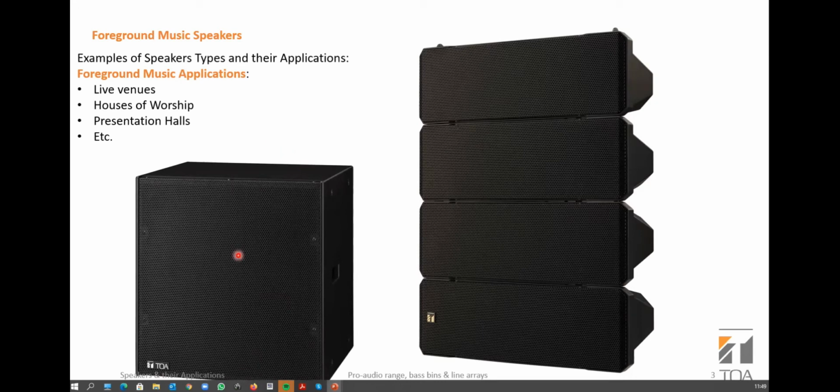So this is when we are talking of seriously high power, when we are using this kind of professional audio speakers, as well as these for live venues, houses of worship, presentation halls, etc. These are normally 8-ohm speakers. You will also notice when we were dealing with the commercial audio side of amplifiers, I was saying 30 speakers for a 30-watt amplifier, for example, 120 speakers for a 120-watt amplifier. In pro audio, it's always an amplifier or 2 amplifier outputs in bridge mode per speaker.